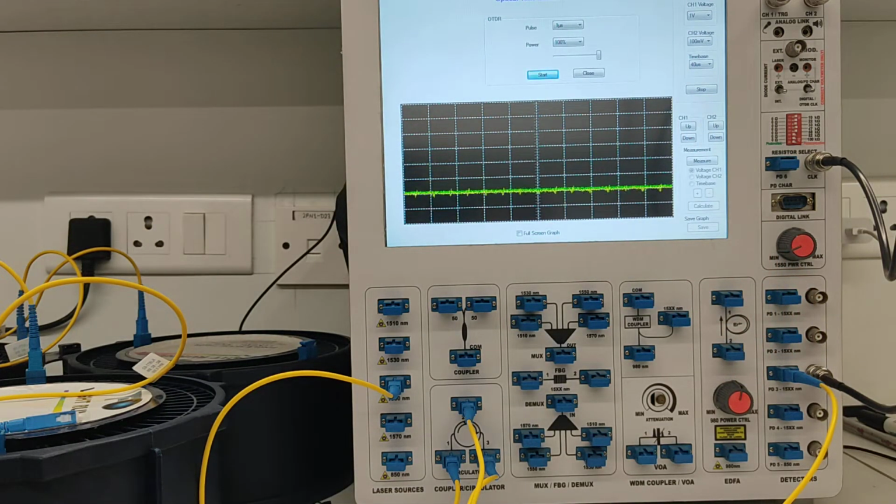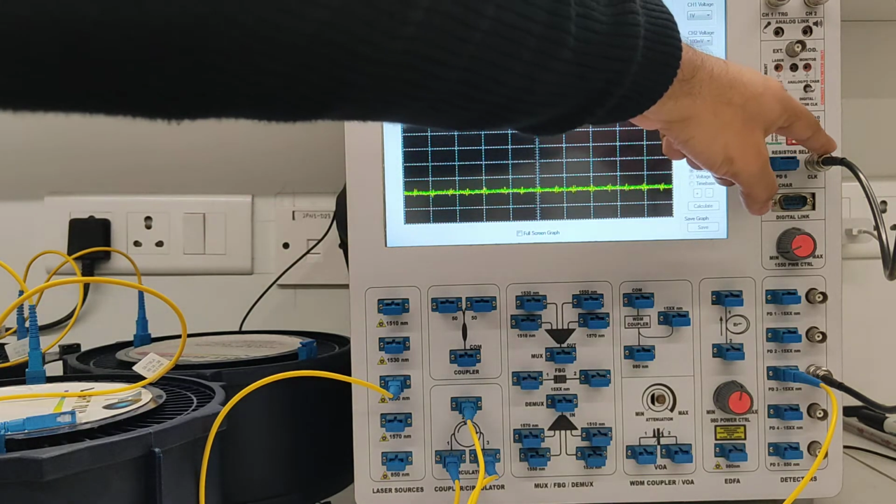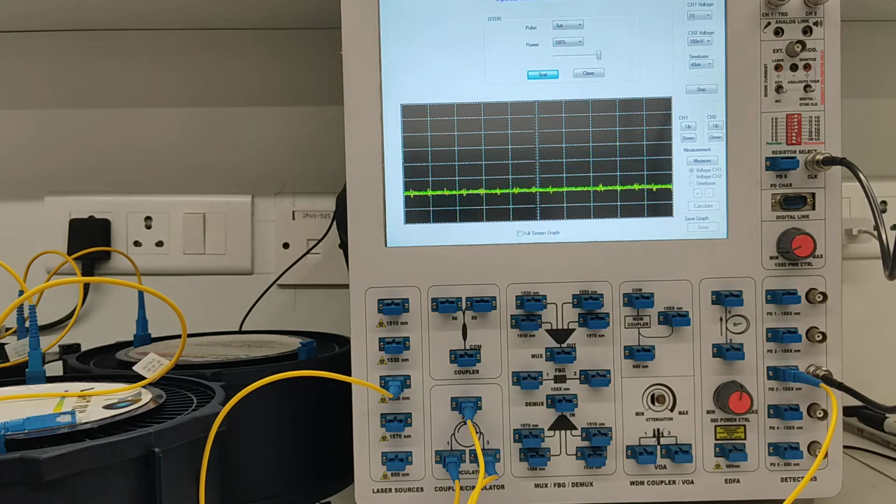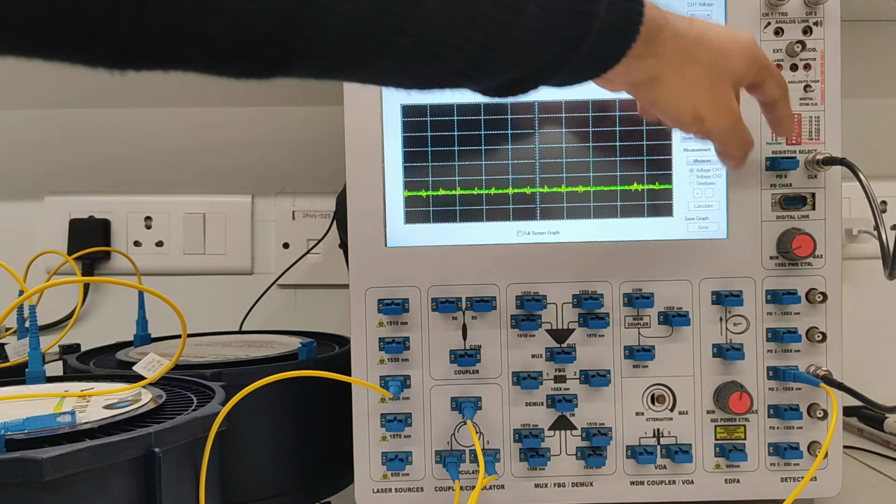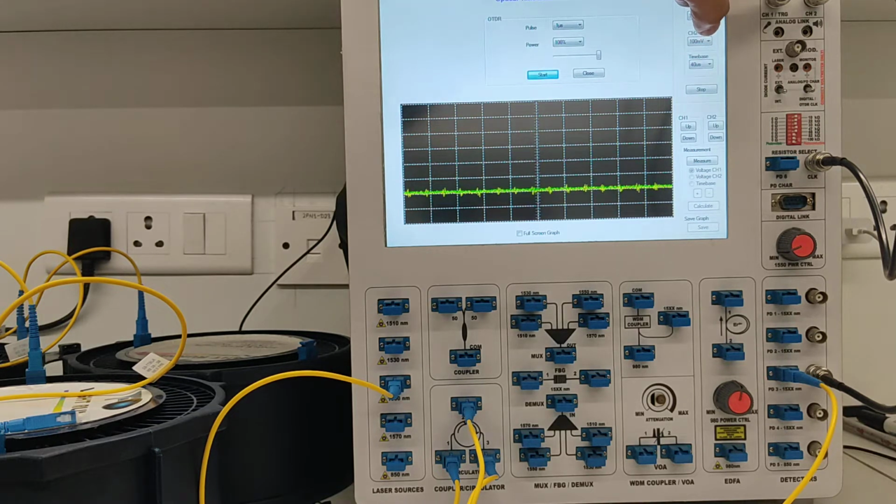So what we will do is make use of the clock, which controls the frequency of the input wave, and we have connected this clock to channel 1, which is also called the triggering channel. So now we can see both the clock signal, or the input signal, as well as the reflected wave.